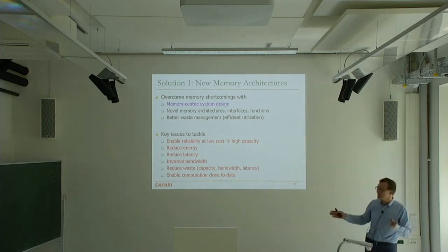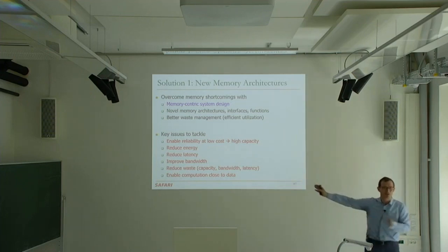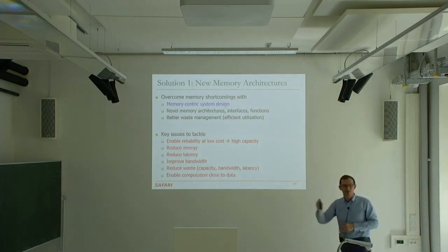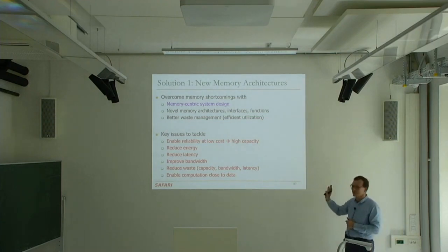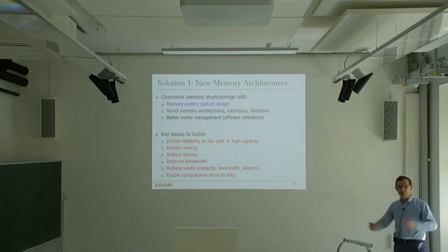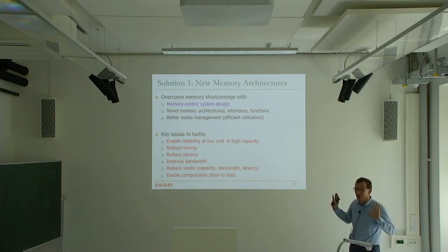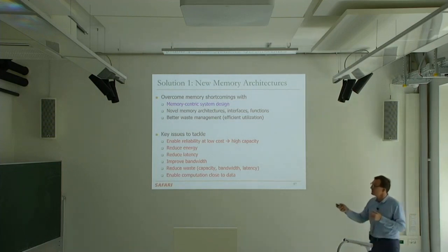For example, the refresh problem. You don't know how often you should refresh DRAM? Refresh it extremely often, right? That solves the reliability problem. Refresh is essentially a reliability problem because you lose charge in the capacitor, right? Basically, refresh it every nanosecond. That solves the problem. But it sounds terrible, right? Or have extremely large error-correcting codes, so that you don't need to refresh it. That's one other solution. But that goes against energy also, and also latency as well.